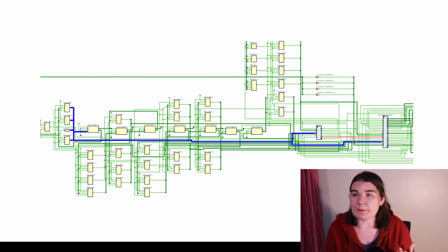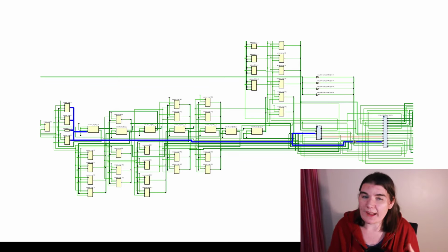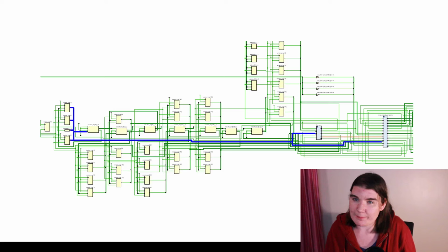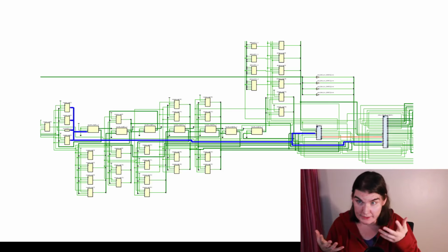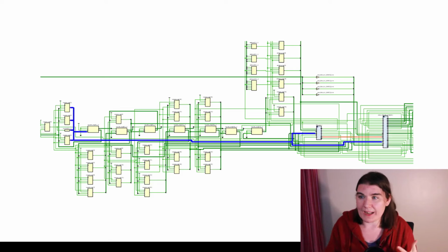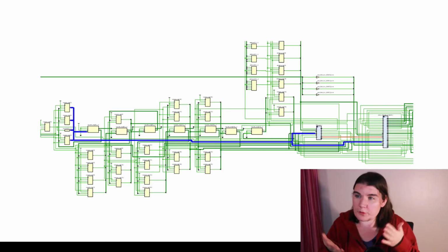And there is a problem that we have inside the FPGA. We have the problem that the signals do not travel through the FPGA instantaneously. There is a propagation time, and this propagation time is through the physical wires, like this blue one and this red one, but also through the blocks inside the FPGA. If you have an adder or a multiplier or some kind of logic block, we have to take into account the propagation time through those blocks in the FPGA.